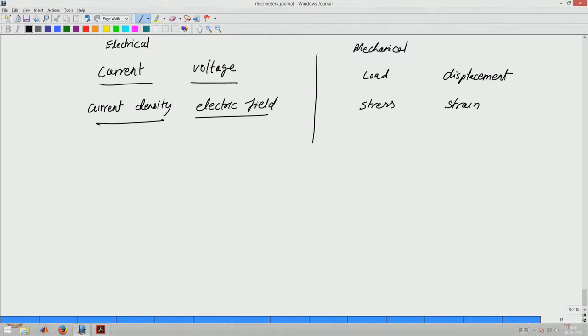what is being measured. And load versus displacement will depend whether, let us say I do a 1 inch diameter rod or if I do 2 inch diameter rod, because load displacement are not material properties, but they are actually dependent on the type of geometry which is being used. But stress versus strain property will not depend on whether I use 1 inch diameter or 2 inch diameter, because they are material properties.